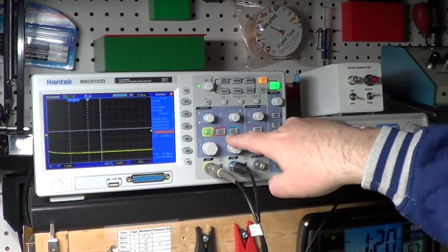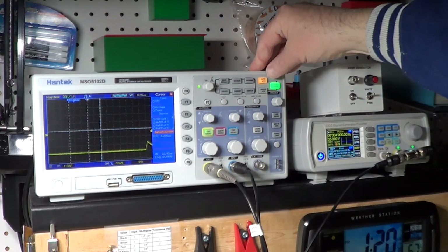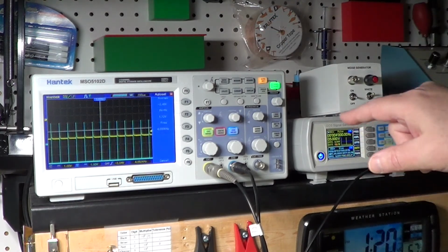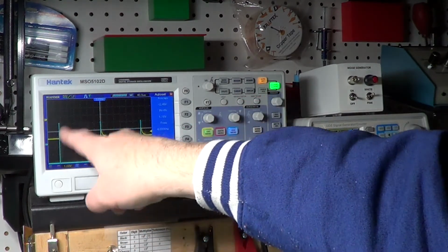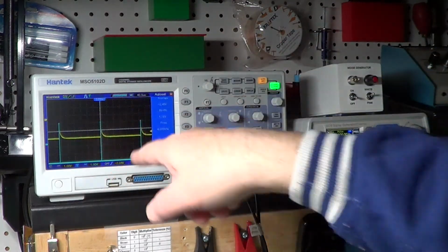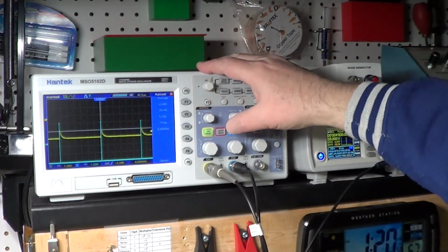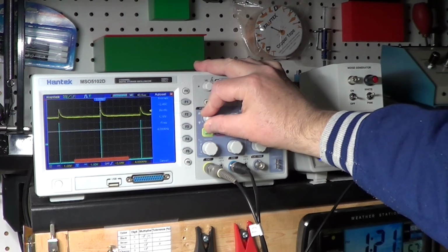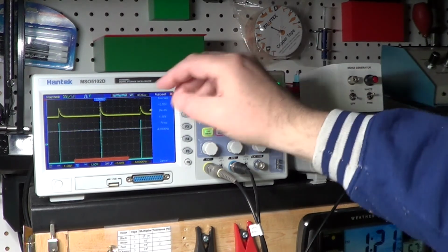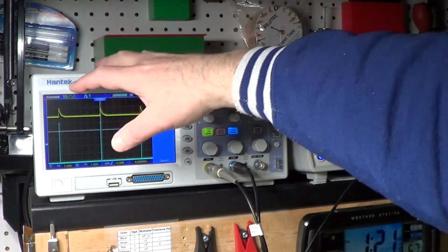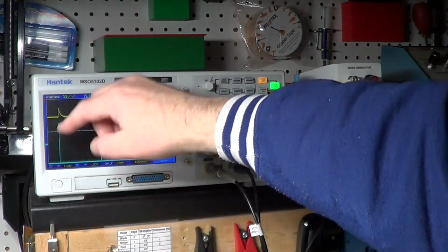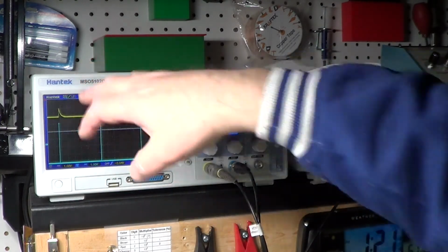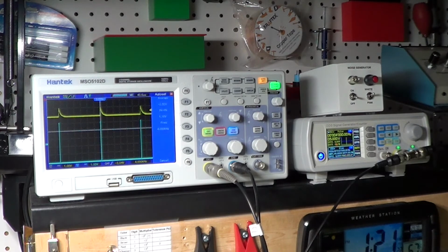So let me go back here and show you the two things at the same time. Here. So these are now the impulses coming from the generator, the blue ones you see, and the yellow ones are the responses at these impulses. Let me put them up so you can see them on top of one another. So you see every time there is a sudden change in amplitude, there is the same sudden change on the output of the filter, but then when this goes away, it takes some time for the change to cancel, and this is because of the fall time of the filter.